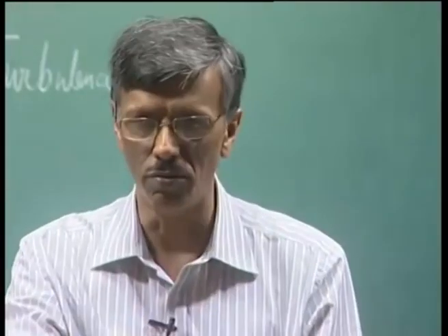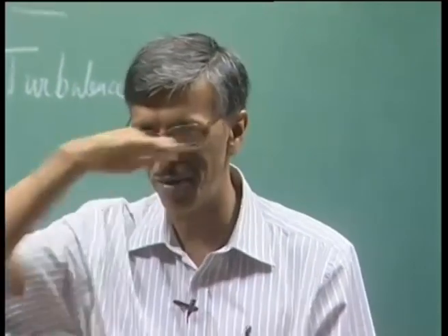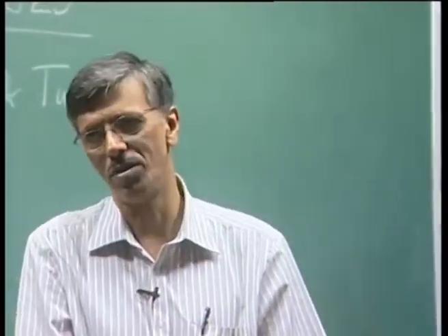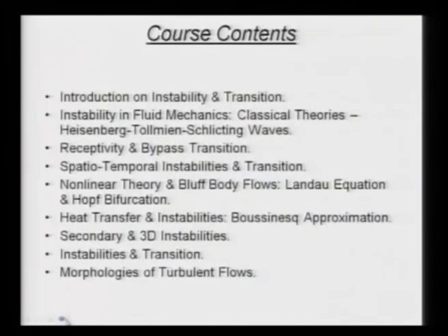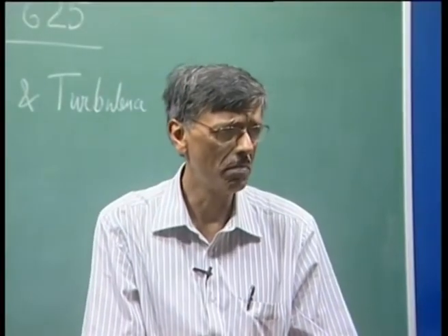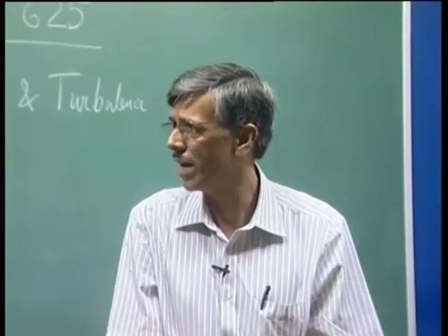Then there is a square flow, shear driven, right. If I have flow between two parallel plates and the top plate is moving, that is what we call a Couette flow. Couette flow is also theoretically found to be stable, right. However, those flows are not really stable. So, people have tried to study, and one of the mechanisms people talk about is some kind of spatio-temporal instabilities that may be affecting some of these flows, and this is what we are trying to look at. Okay.